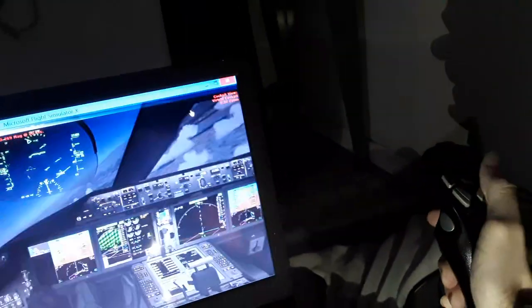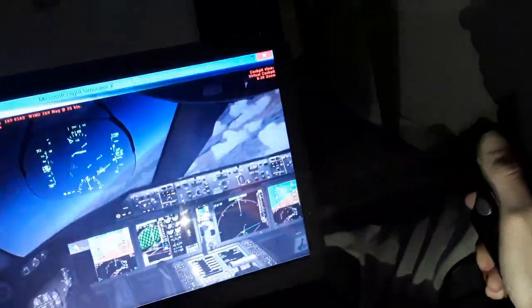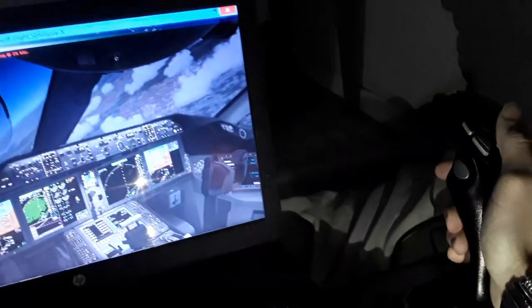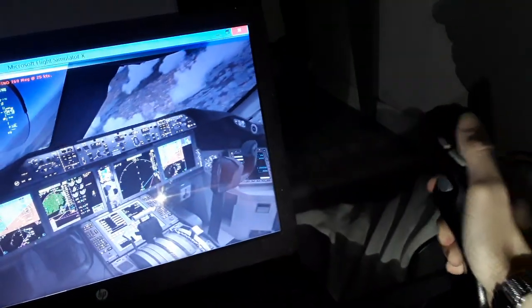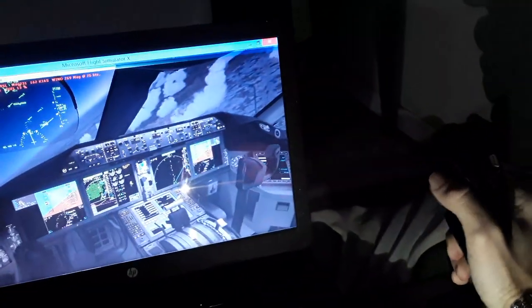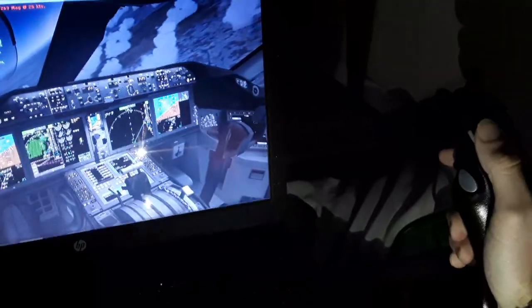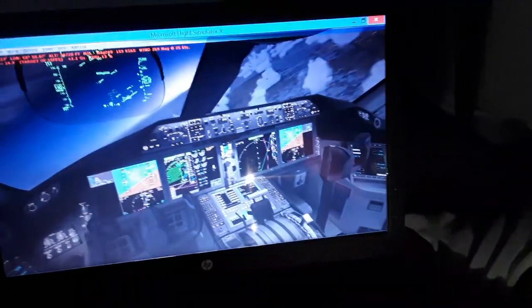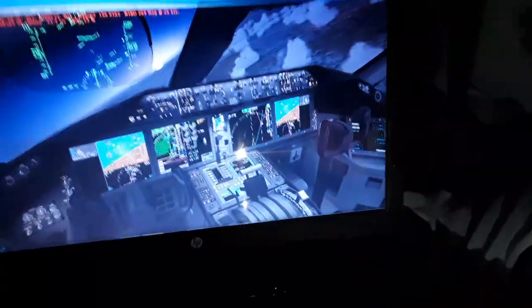And make a turn also with the right pedal. Use the right pedal to make a steeper turn with a lower airspeed. Right now we're very close also to the stall speed, as you can see, this margin. So we need to be aligned again with these lines here for approach and landing.